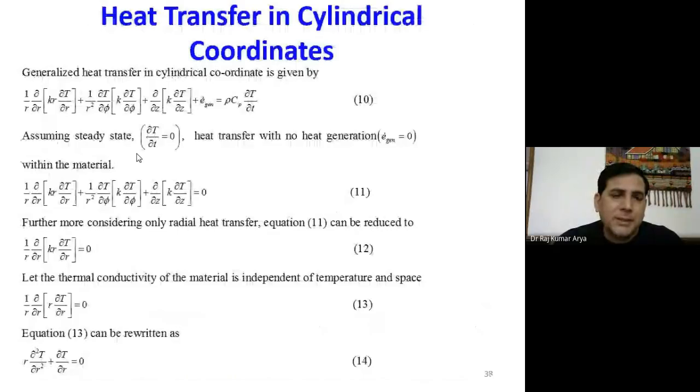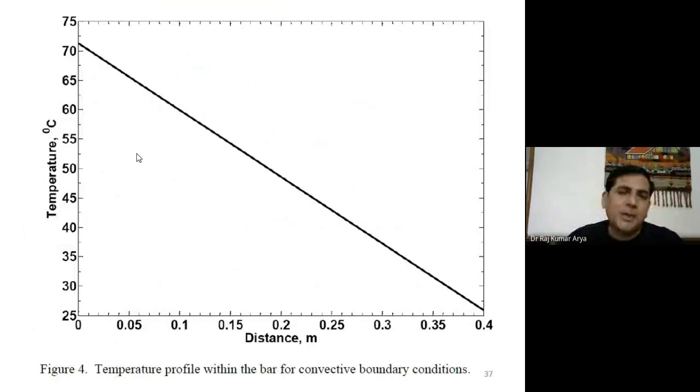Now we actually did two types of problem. Generally we have only two types: either you have a temperature boundary condition or a flux boundary condition, right? So we have taken two distinct types of condition, either temperature or flux. Now you can mix them up, so you can have one side in temperature and the other side in flux. You should take care of the part where you have flux. It will just add something to get the boundary temperature in terms of the flux boundary conditions. Substitute that, and you can write a separate program by just changing a simple command. Once you wrote for one case, it's not tough for the other case. Fine. Yes, sir.